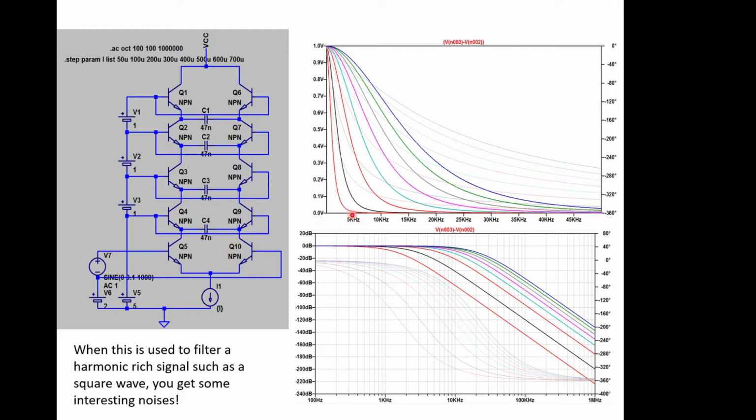that as we are changing the bias current down here, the values of I, the frequency response, which is normalized here, starts to change. So this is the linear response, and you can see the cutoff frequency is around about here. For this particular bias current, it's around about 15 kilohertz, and as you increase the bias current, the cutoff frequency drops right down. So that's what it looks like in linear terms.